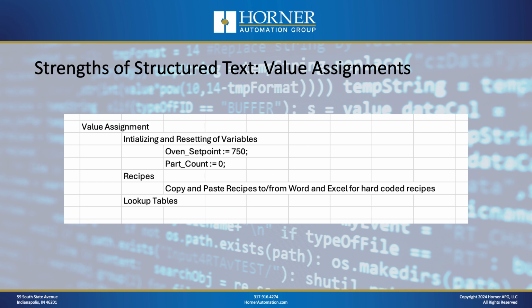And a thing a lot of people forget is you do not have to write structured text where each assignment is on its own line. I could have 4, 5, 6, 7 value assignments, values to variable assignments, done in one line of text because the semicolon is the delimiter for that. So that's important in terms of assigning values to variables.